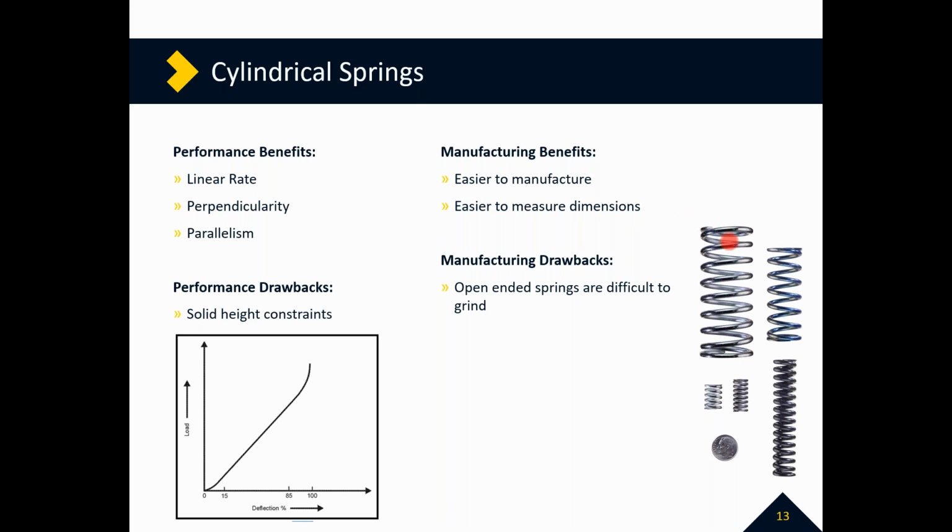and they're easy to measure. As we all know, you could take a pair of calipers to it, measure the length, the OD. Drawbacks, and again, wouldn't see this in relief valves, but we do have customers on just other applications that want open-end springs, and sometimes they want them ground, and it's not practical. Open-end springs tangle really bad. Grinding them is even more difficult because you don't really have a square or flat surface to come into when you grind it.